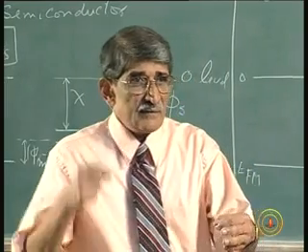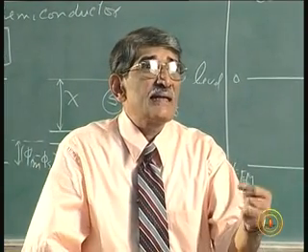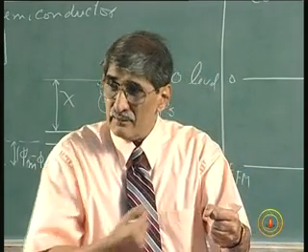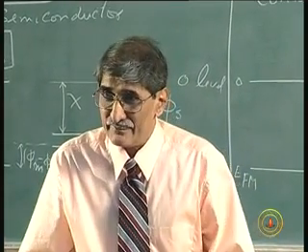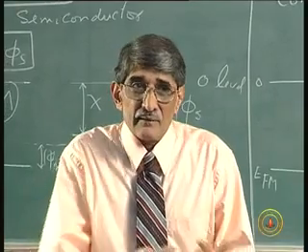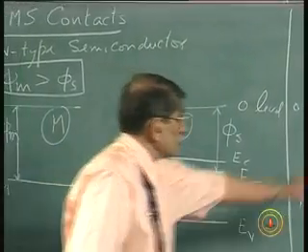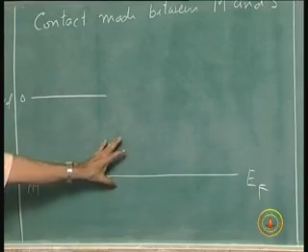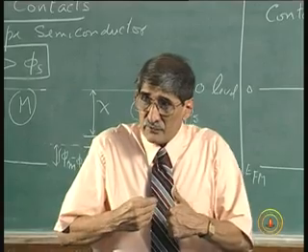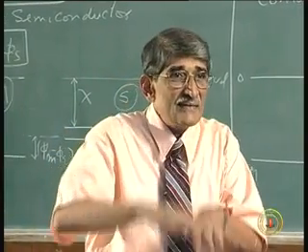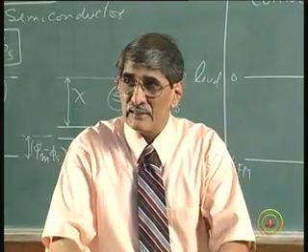Plus charges are there, so you can easily move. If a point is negatively charged, it becomes difficult to take the electrons because it will repel them, so you have to spend more energy. So, the very fact that you have removed electrons from here and pushed them to the other side, you left that side positively charged. It becomes easy to take electrons to those levels. That means all the levels in that region have gone down in energy.